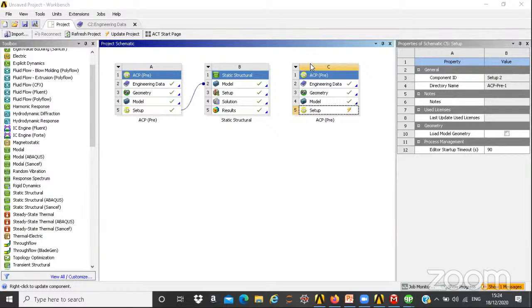For example, for automation, let's say I want my surface roughness to not rise above 1 micron while machining some composite. I need to model the system using a transfer function from control theory, and based upon it, I can apply controllers like PID, fractional order PID, or any advanced controller, and tune those controllers so that the input parameters, such as cutting parameters or machining parameters, and even material parameters depending on the experimental design, are controlled automatically in such a way that the output is always 1 micron.